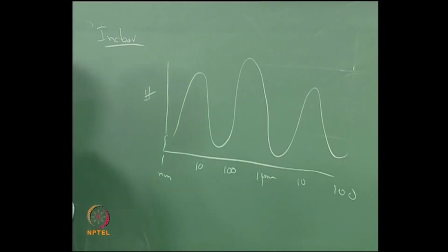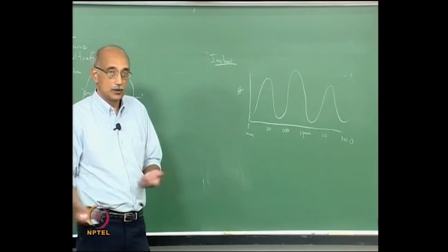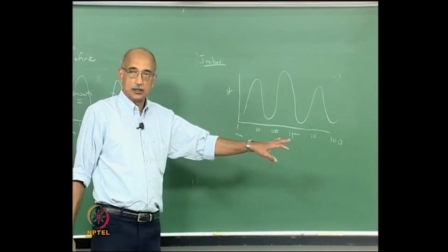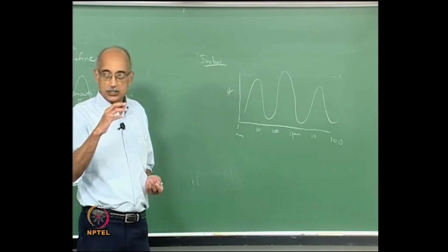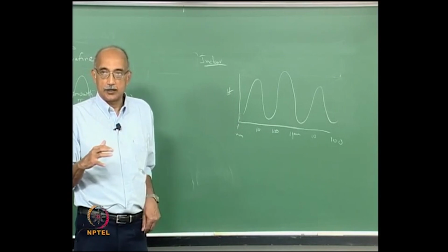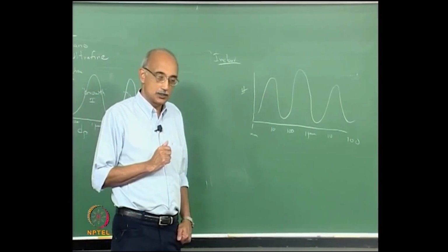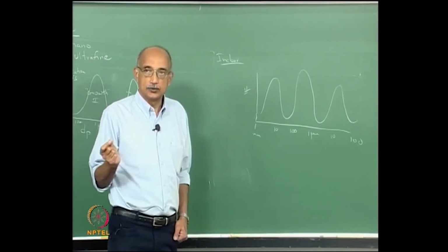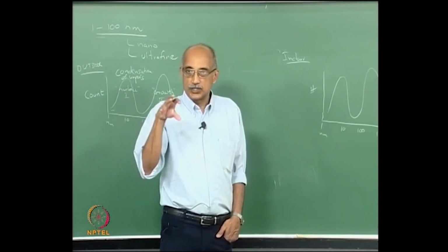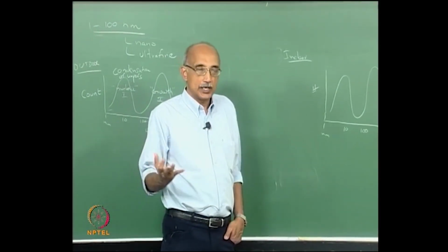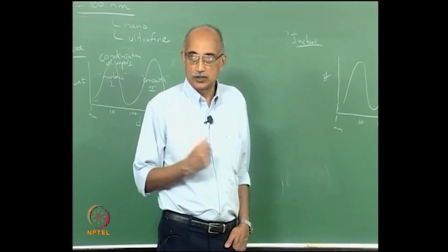Again, the actual magnitude of the peaks, the scale itself can change significantly. For example, if this is a clean room, a clean room is a facility that is designed to operate with a very fixed level of contaminants in air, including particles. So for example, and we will discuss this in more detail in future lectures, when you talk about a class 100 clean room, what it means is that per cubic foot of the air that's inside the room, you can have no more than 100 particles that are 0.5 microns and larger per cubic foot of the air.